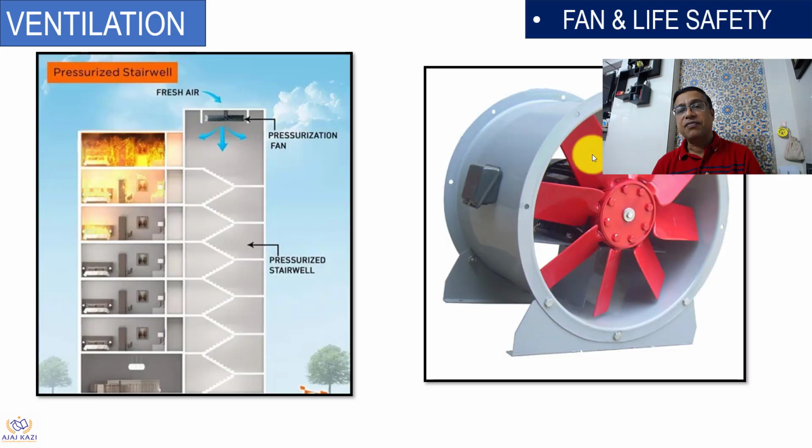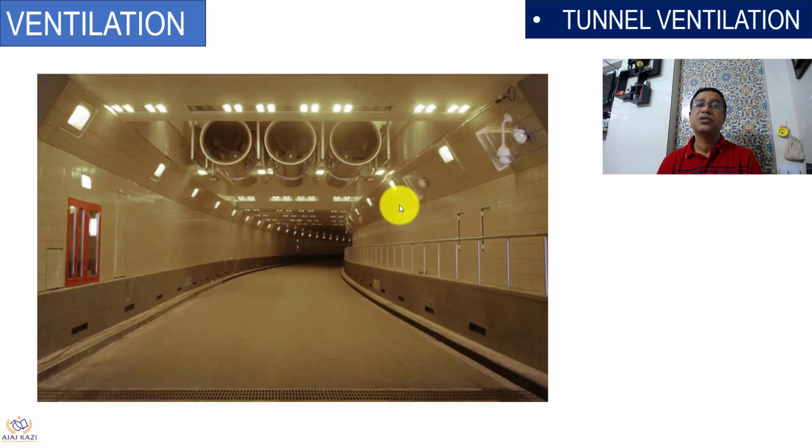Fan and life safety, I spoke about. Generally, we get fire rated fans for such application. Otherwise, the fan will not work in case of fire. So they have to be rated. They have to be tested by certain agencies.